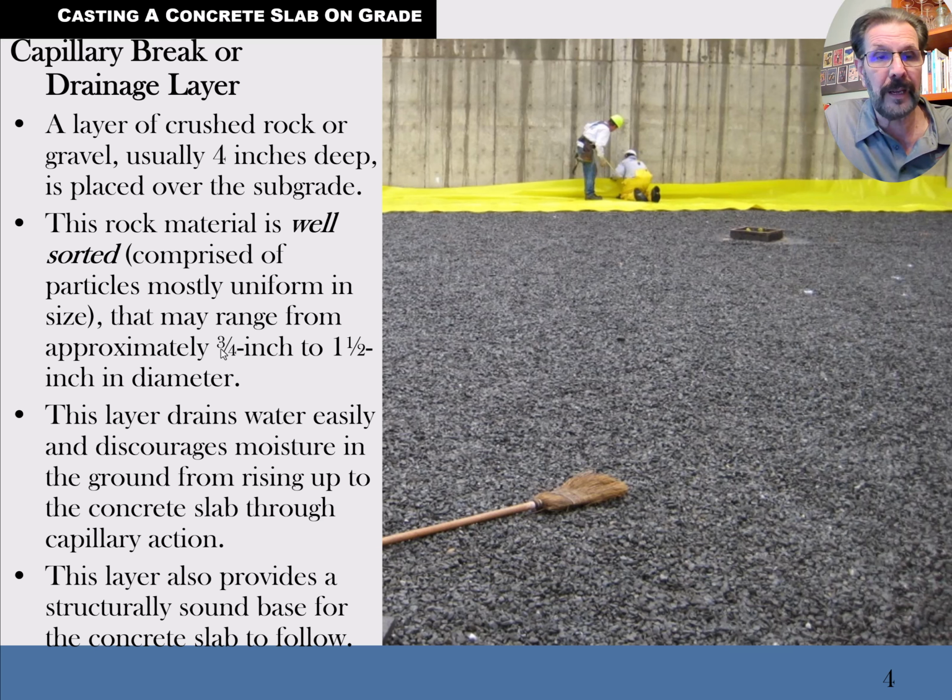Now, a trash bag or a lawn and leaf bag will be about 1 mil thickness of plastic. A contractor's bag would be twice as thick as that, about 2 mils. And so when you talk about 6 mil, it's pretty thick plastic. That said, ACI recommends 10 mil thickness on top of concrete. ACI is the American Concrete Institute. They're kind of the authority on concrete in this country. I'm a member, but it's made up of a lot of structural engineers and such, and people in the concrete business. So there you go. That's slab on grade.